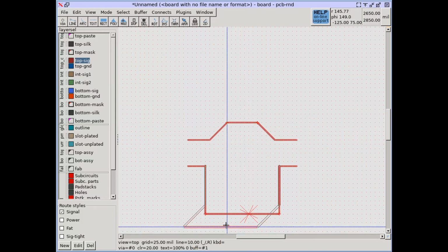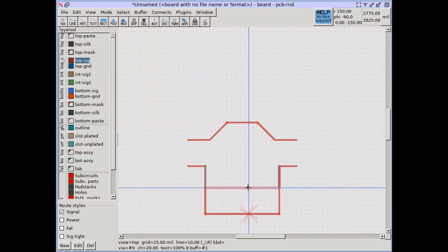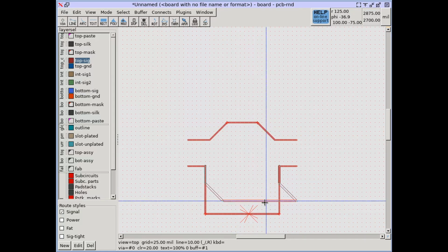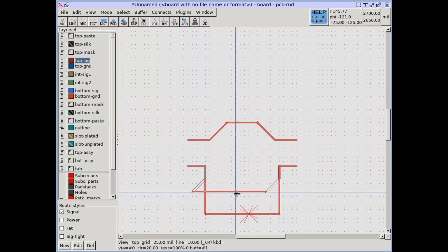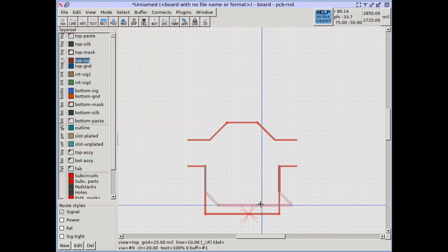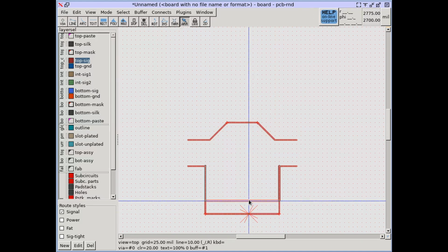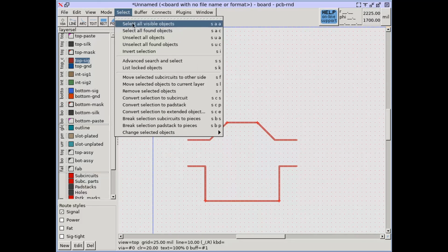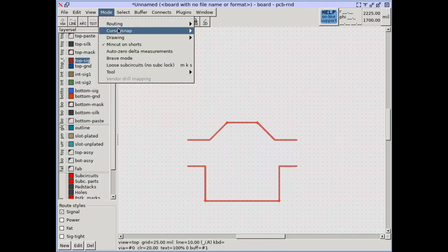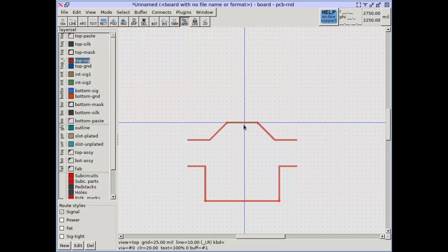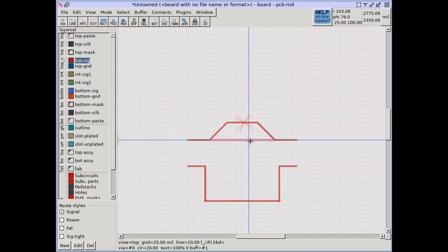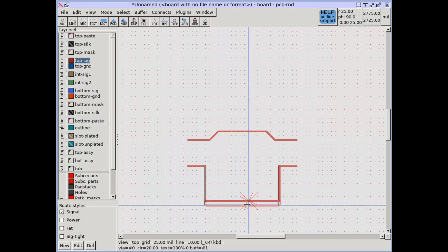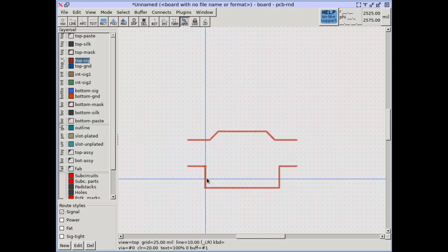A middle segment is a line or arc with both ends connected to other lines or arcs. Standard rubber band mode allows moving a middle segment in any direction. When the rubber band keeps middle line DIR option is enabled, the middle segment is constrained to move only orthogonally. This makes it easier to fine-tune complicated traces without accidentally moving segments sideways.